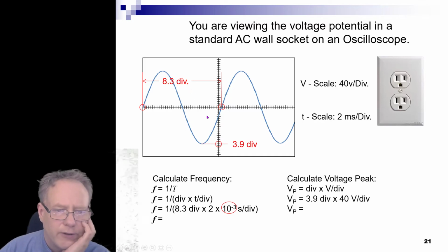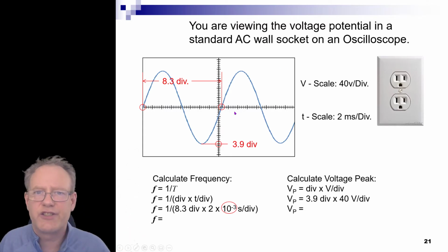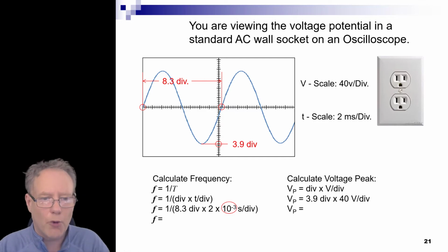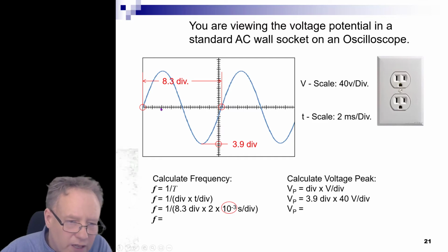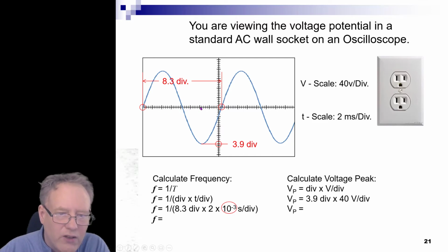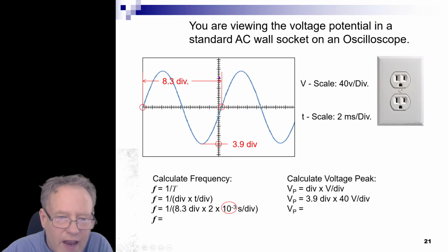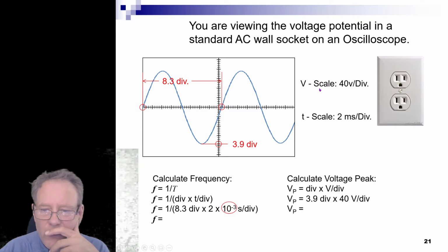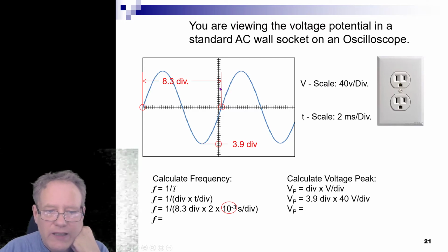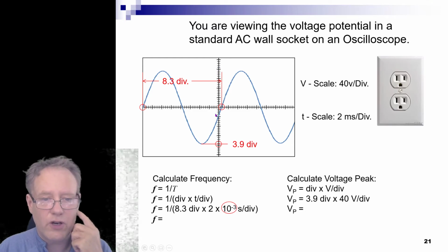What we've got here on the oscilloscope, remember, it's scoping oscillations. Okay, good. So we're scoping the oscillations, and each one of these scales represents something. Each one of these divisions has a particular value. From there to there is worth something in time, and from here to there, it's worth something in voltage. So the voltage scale is 40 volts per division. In between here and here is 40 volts, and it's consistent.